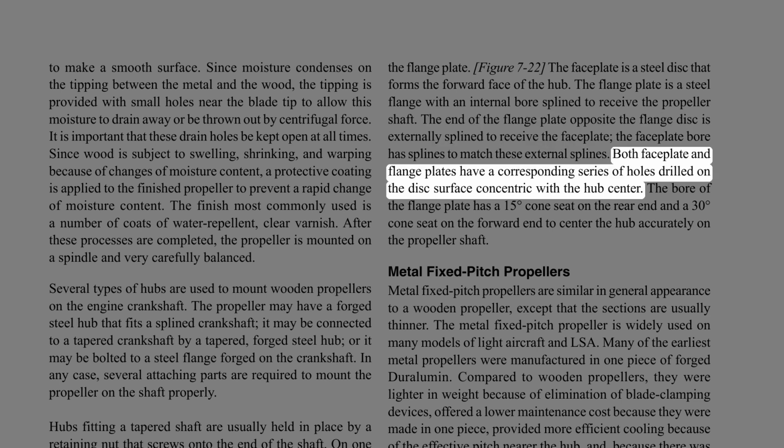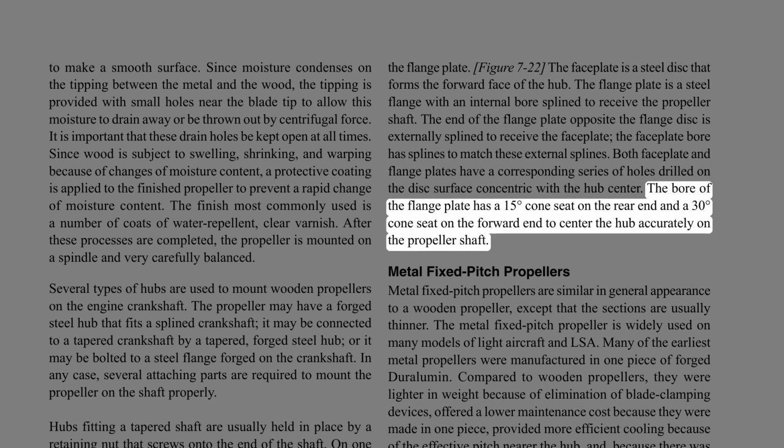Both faceplate and flange plates have a corresponding series of holes drilled on the disc surface concentric with the hub center. The bore of the flange plate has a 15 degrees cone seat on the rear end and a 30 degrees cone seat on the forward end to center the hub accurately on the propeller shaft.